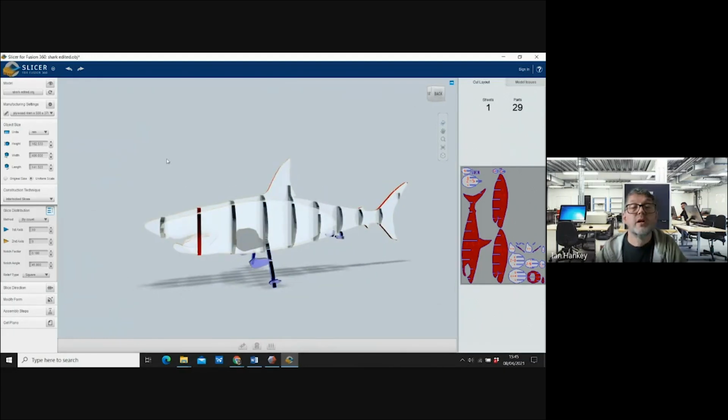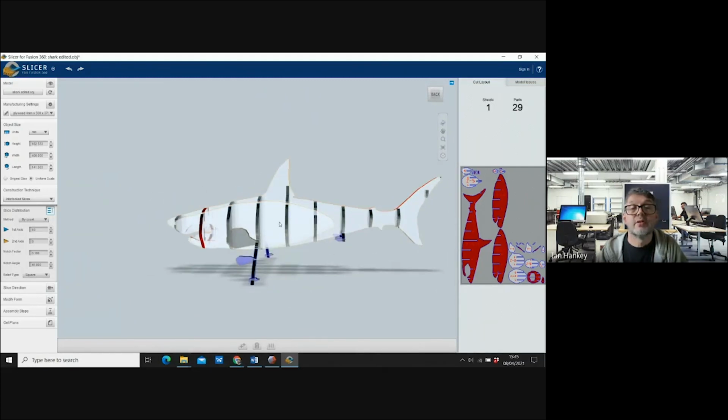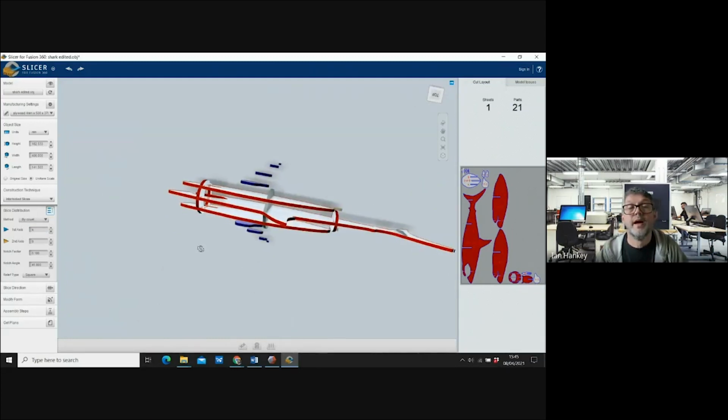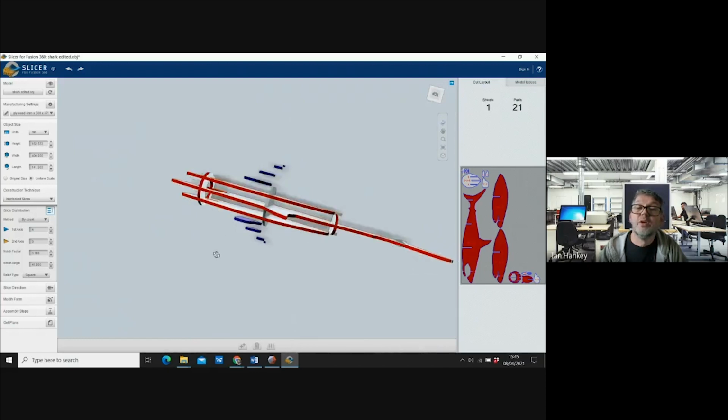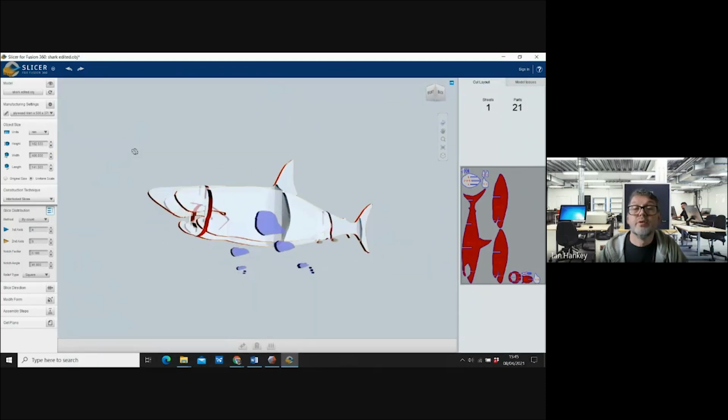Also, let's have a look at the other one. Let's look at our first axis, which says 10. Now these are the ones that are going down across. We can change that 10 to 4 and click in dead space, and now we've just got those 4. Again, absolutely impossible. Now you can see the problem I'm talking about with the fins. There's nothing to actually link them to the central model. And so it's showing that in blue, telling you there's a problem there, but it's still given us a plan for it.